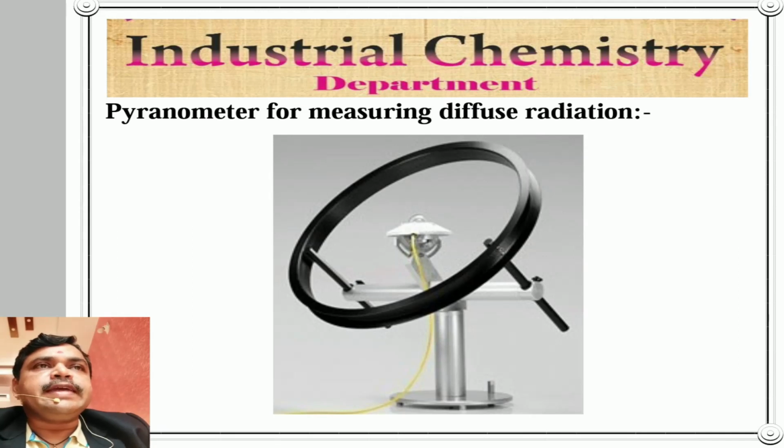Two concentric hemispheres of 30 mm and 50 mm diameter, made of optical glass having excellent transmission characteristics, are used to protect a circular disc of 25 mm diameter in any season. It can also be used to measure diffuse radiation. This can be done by measuring at the center of the semicircular shading ring.